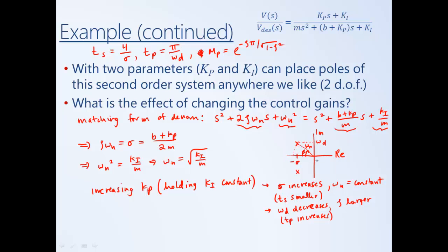When our poles are real, when our poles are on the real axis, we have no oscillation at all. So that's the most damping you can get. When our poles are on the imaginary axis, they're purely imaginary, they oscillate without decaying. So that's the least amount of damping we could have. And so that's one way to remember what the effect of beta is. So big beta takes us closer to imaginary poles. Small beta takes us closer to real poles.